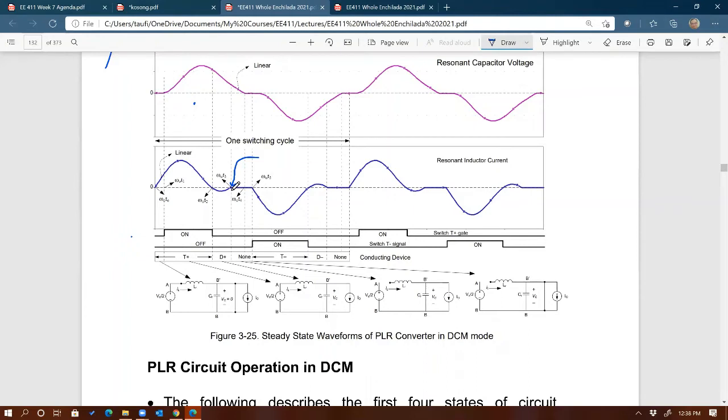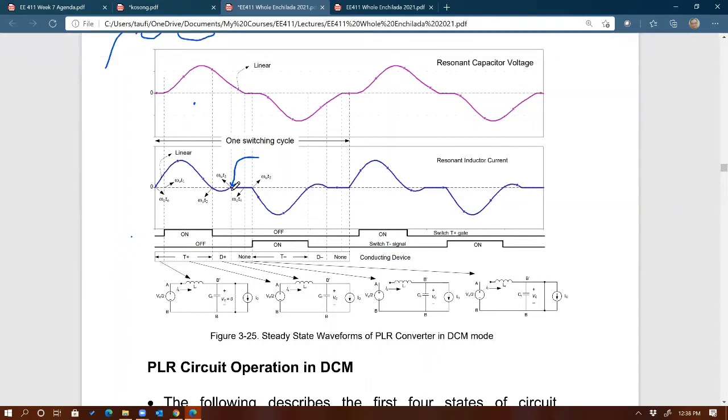So since it is naturally going to zero when it's turning off, right when the diode is turning off, the current through the diode is 0 amps. Therefore, there's not much reverse recovery that the diode has to do, because it's 0 amps to begin with. It's not turning off at some high current. It's turning off at 0 current. So the reverse recovery time will be very fast. That's the reason why you could use a slower diode in this case.